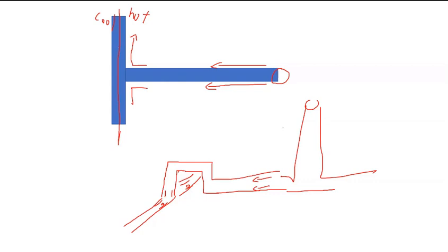So it doesn't have to be this shape. I also see something like go down and go up. So the idea will be to try to add something to make the melt front go in the vertical direction. I also noticed in some good hot runner systems, they will always have a hot runner, maybe like this one.